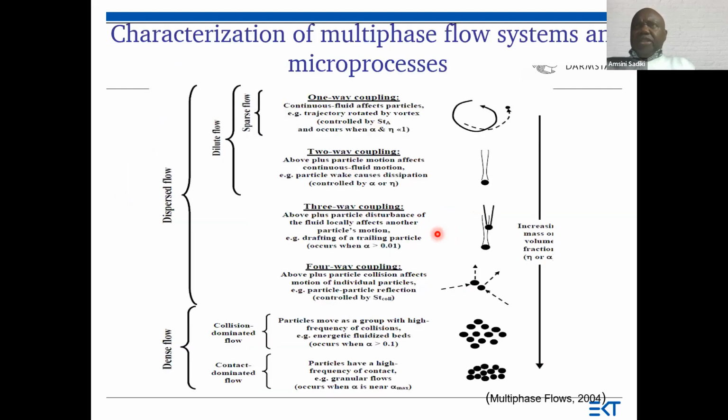So at this point, I would like to put everything together. We have the one-way coupling, the two-way coupling, and the three-way coupling, as I told you, because if the particles are large, then we have the wake flow, and this wake can also influence the flow field behind the next particle, so that we have three-way coupling.